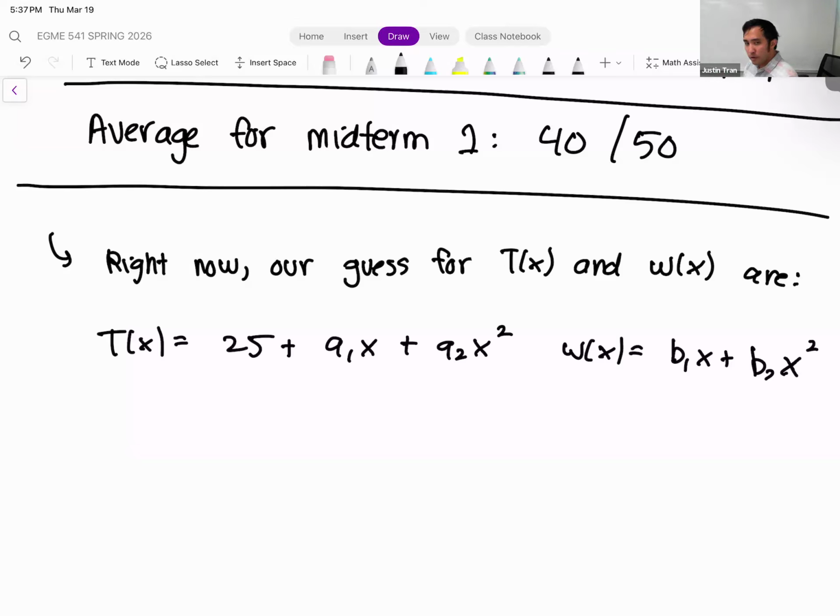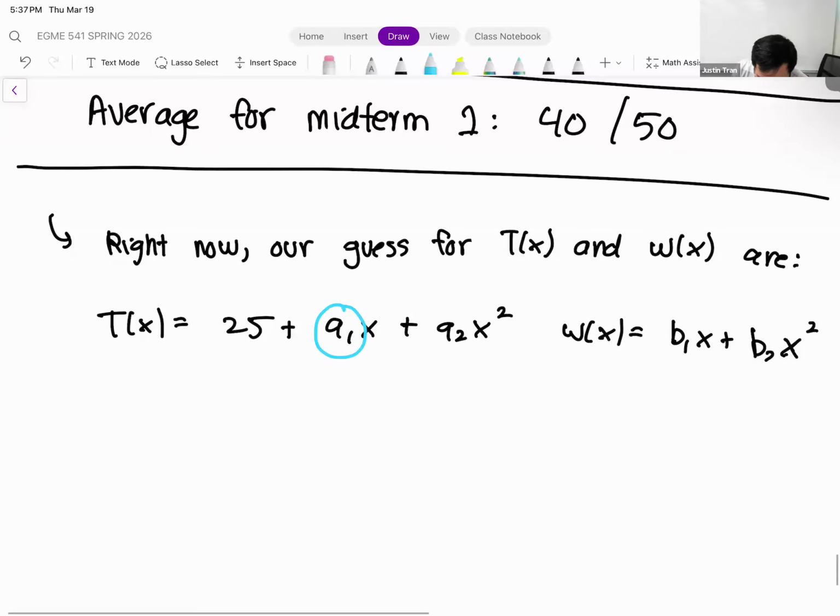So we've solved for A0, but in order to complete this problem, we also need a solution for A1 and A2 as well. And so the way that we're going to solve for these is that we're going to plug these expressions into the weak form of our boundary value problem, and then work through the algebra and the calculus, and eventually we're going to get expressions that we can use to solve for A1, A2.